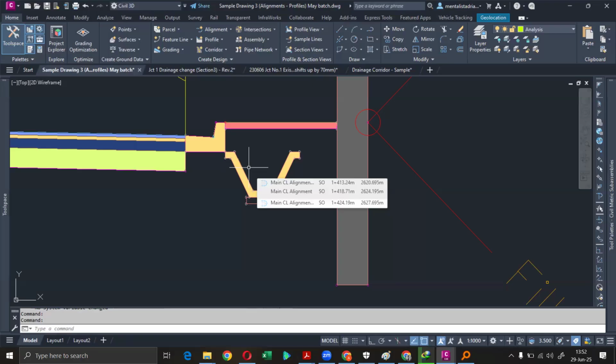Unless maybe, if you have little space, you could introduce a median, and in the median you use it as a drain. I think there are sections of the northern bypass where you will find a drainage in the middle of the road. That's only enough where there's space. The situation is that I've seen someone saying for the road, always say residential.